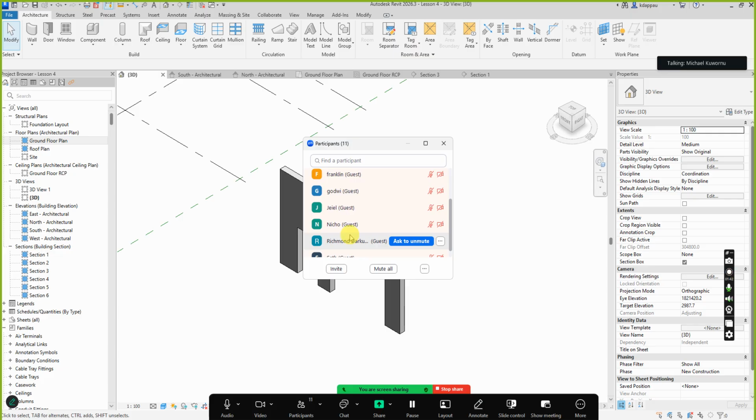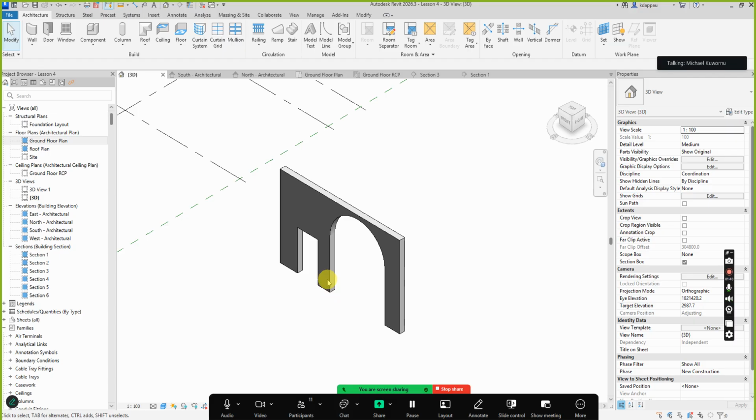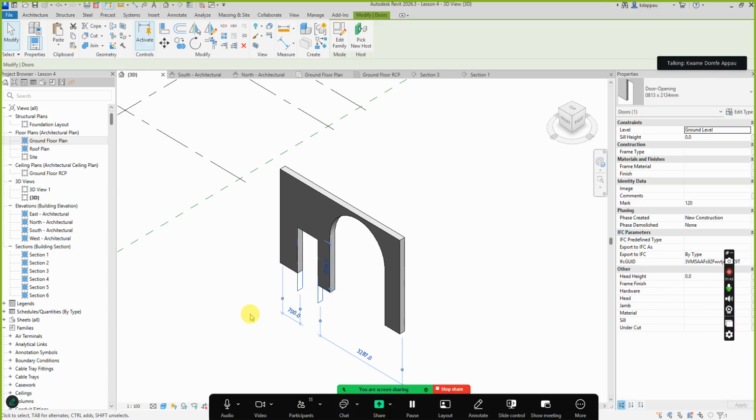But I use it for small modeling, and I edit the walls like you are saying. I've not been using the arches there. The arches, yes. From my experience, most Revit users feel very comfortable editing the walls in profile. It's a very, very bad practice.